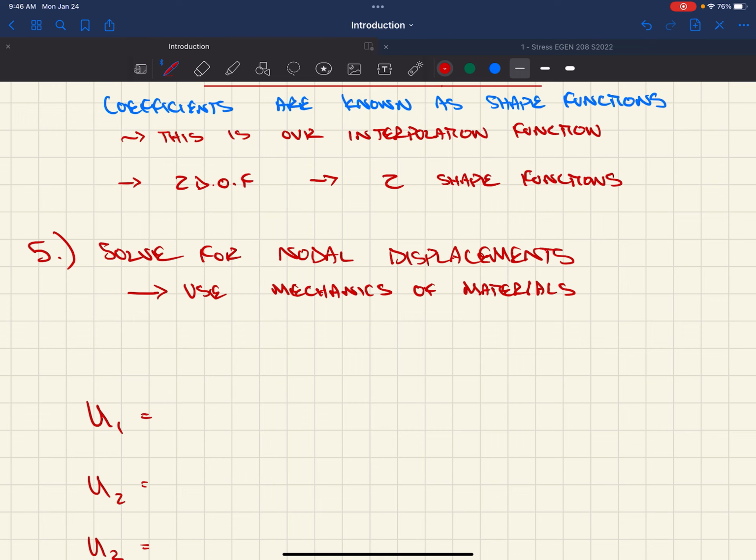As I mentioned, separated up into discrete regions, finite regions, we algebraically calculate what our nodal values are, and then each of our finite elements, if we select a finite element, that finite element has an assumed field variable interpolation function. It's essentially just saying, I'm assuming that if I know the end values, that the value between them changes in a certain manner.